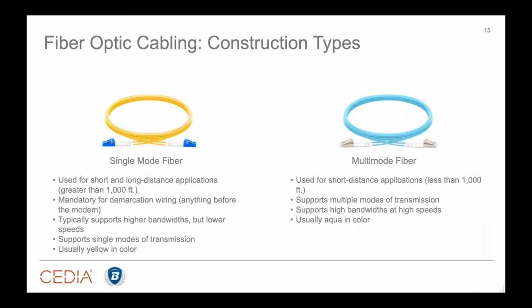Now, you also have to choose the right fiber. And there are two different types. The good news is these are color-coded. You have single mode. That's the yellow cable. If you've ever been on a project and you've seen a yellow fiber optic cable, that's single mode fiber. And then you have multi-mode, depending on the grade, we'll get to that in a minute. Multi-mode can be aqua, violet, or orange. Most modern cable that you're seeing integrated today is aqua. Multi-mode OM3, very standard, okay?